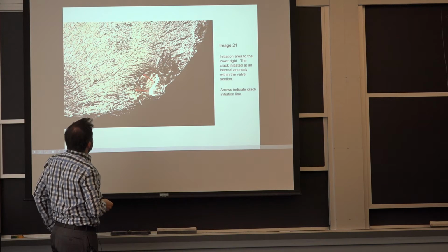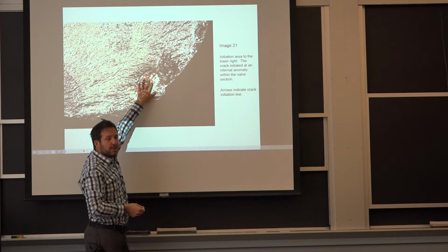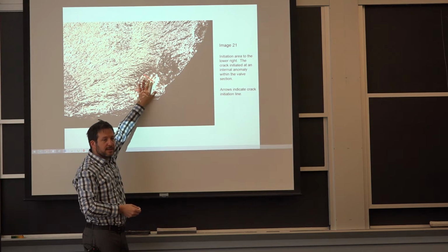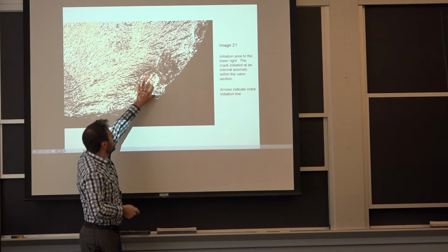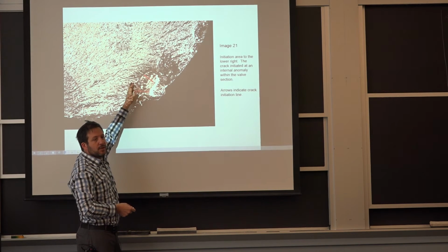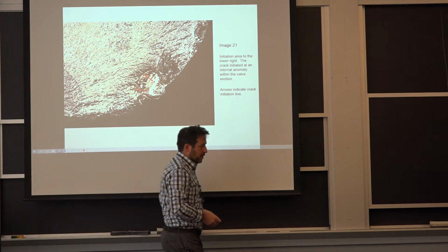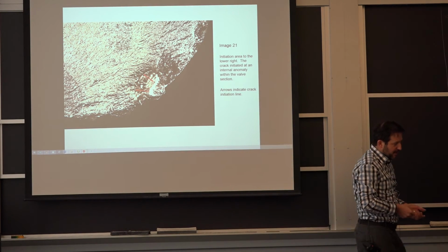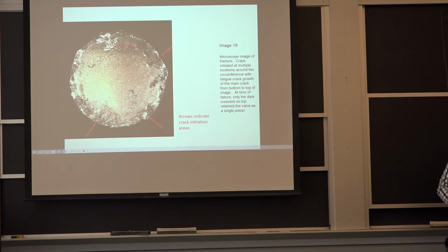So what it tells us is you had this corrosion pit, which is big. This is almost 0.5 millimeter. It's visible. That happened first, and then you had these cracks starting from it. I bring this one up because it's a simple way, and you can see it once these parts were clean.